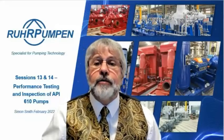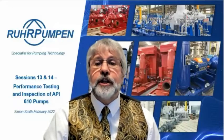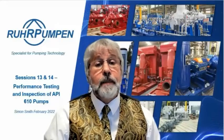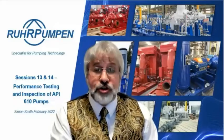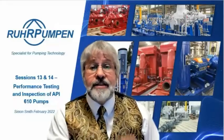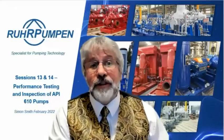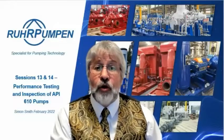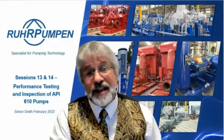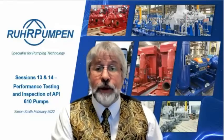Dear Simon, many times manufacturers have performed tests with the motor for test. Is it mandatory that the pump be tested with the main motor? No, there's two problems with testing with the contract motor. The first is that it might not be big enough. If you're taking a hydrocarbon pump operating with an SG of 0.7, for example, the motor is sized for 0.7 SG. So if you test it with water, with SG 1, you might be overloading it.